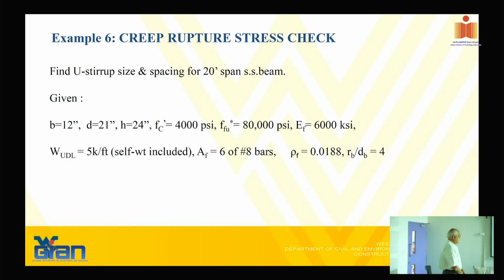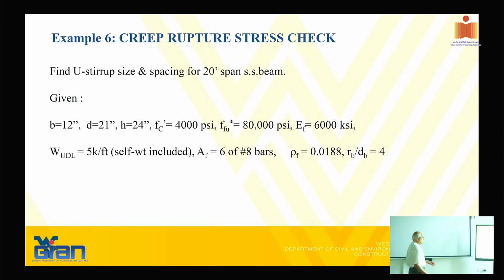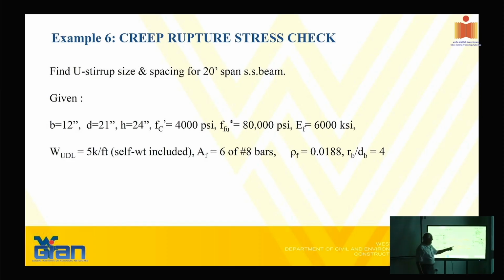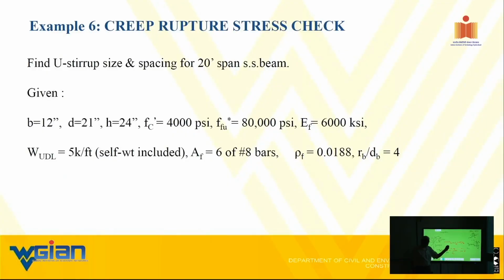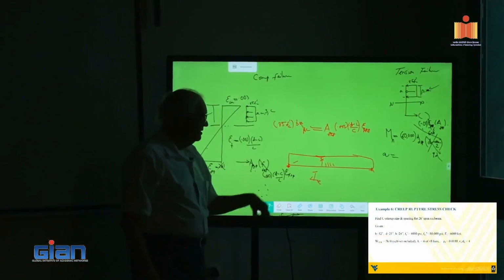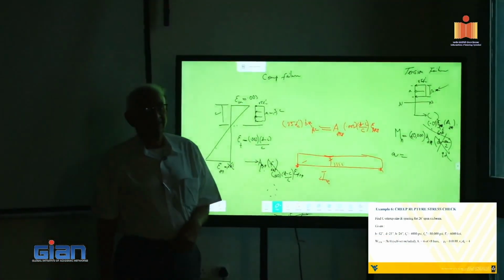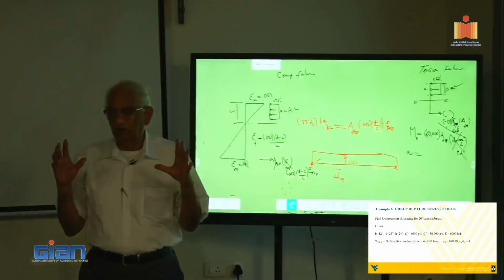So while we are at it, all I want to say is we talked about the bending cracks going from bottom up, and at some point the concrete will crush, and the effective depth of the neutral axis for steel is about 15, 16, 17%. For FRP it is about 8%. Whereas the shear crack is going to be something like that. And this is where I want to repeat myself.